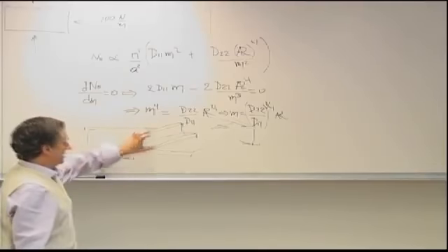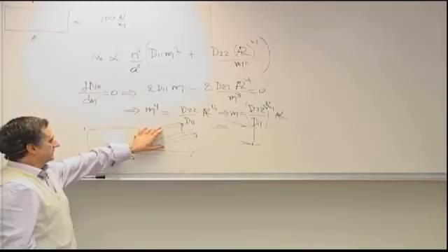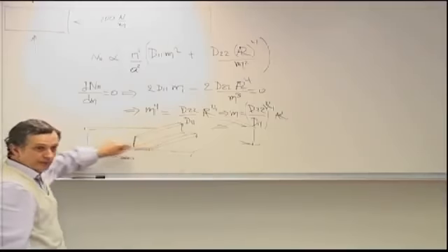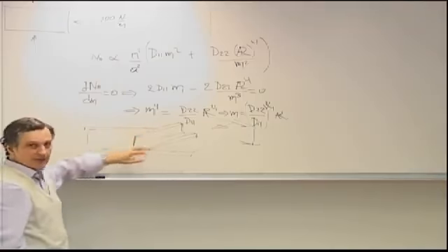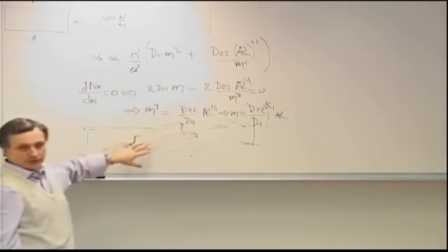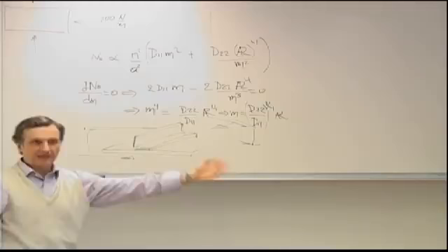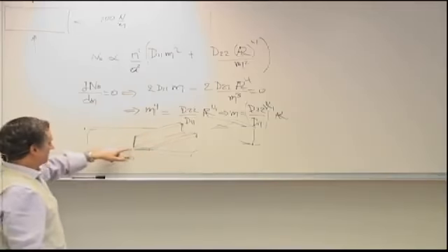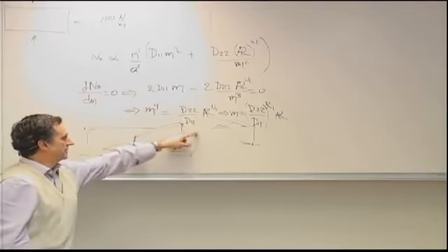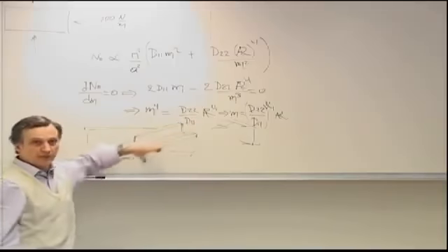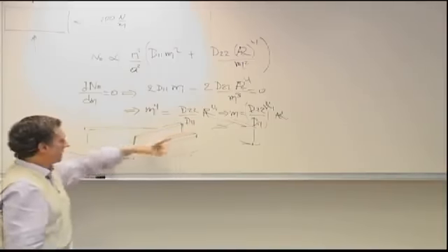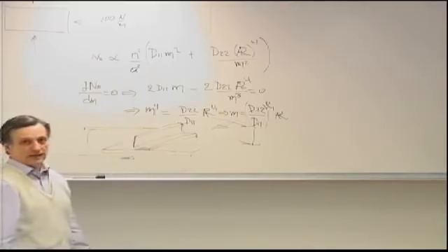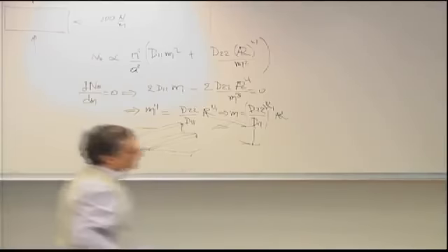analyzing the stiffeners under compression would require us to find the individual loads on the individual members and then decide what the boundary conditions are, and then go into some kind of a buckling analysis if it's compression. So the typical case is simply supported at the two ends where it's loaded because that's where it's held by adjacent structure, and simply supported on one edge because it goes into a web, let's say. So that's the reasoning behind this.